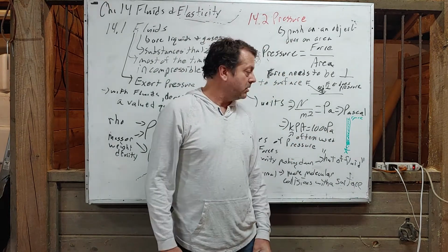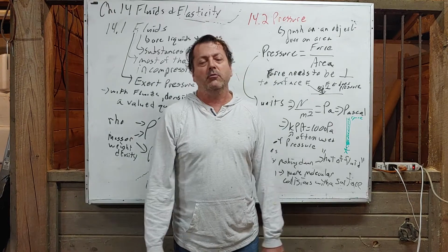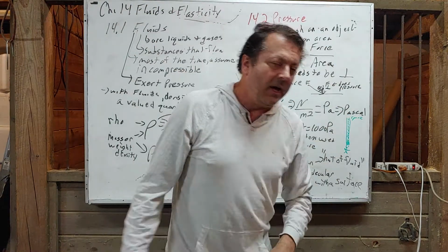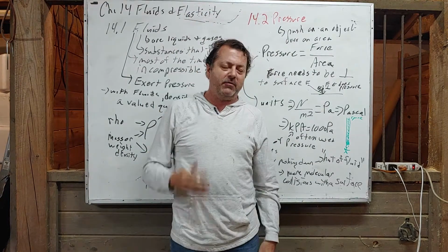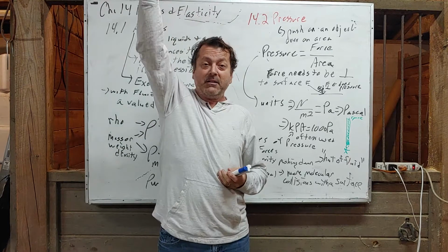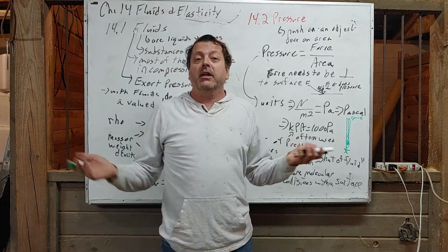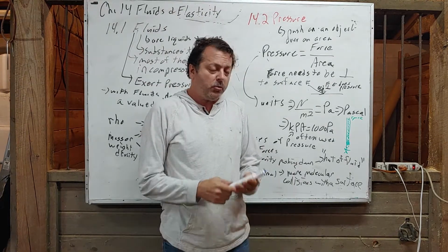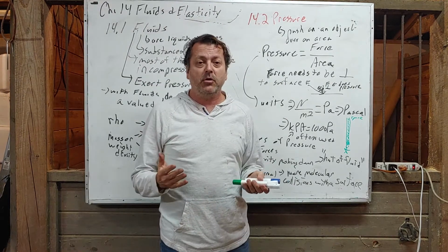It's on top of us. I'm wearing a hat of air right now, and everywhere I go, there's a hat of air walking with me. I walk through it, but I've got the same hat of air. If I go up in elevation, I have less length on my top hat, so there's less pressure on me. But that hat of fluid on top of me is what causes pressure on me.